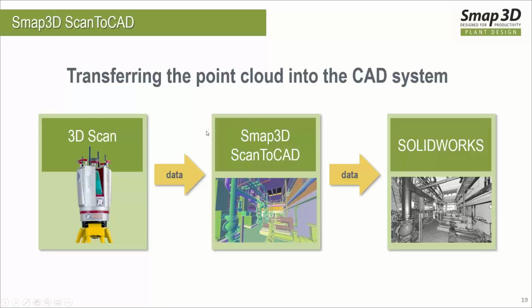Instead of trying to import a whole point cloud into SolidWorks, which generally doesn't work so well in our experience, we can pull it into the scan to CAD and selectively tell it what's important to us, and then only import that data into SolidWorks as native SolidWorks features. So we don't have to deal with any tessellated data or mesh files inside of SolidWorks, and only pull in what is important to you out of that scan data.